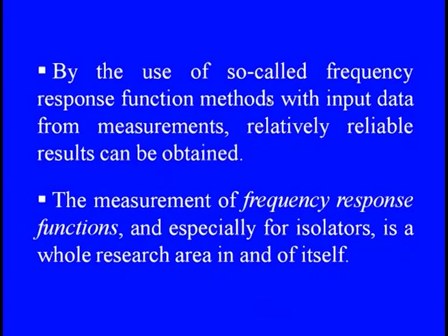If we are using the basic vibration theory, we need to use the frequency response functions, meaning what the exciting level is corresponding to the frequency itself. From these measures, because we know that whatever vibrations are coming have some kind of stationary feature, these stationary signals can be straightaway characterized using these frequency response functions.